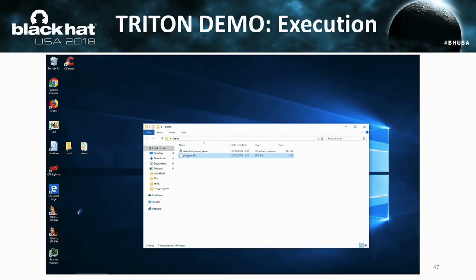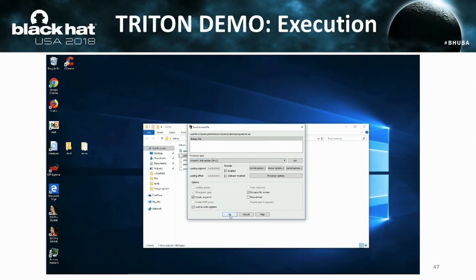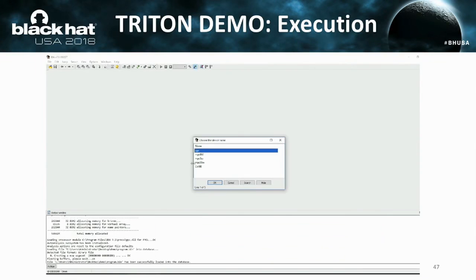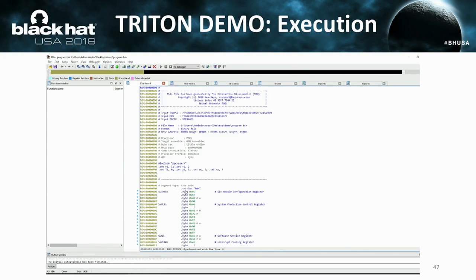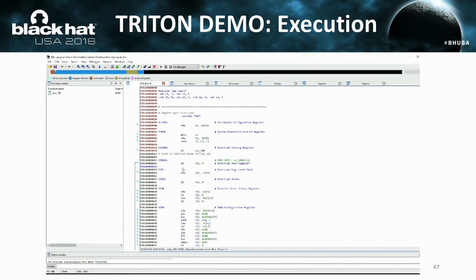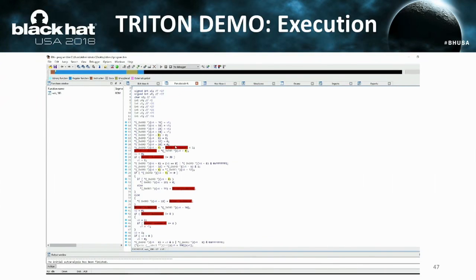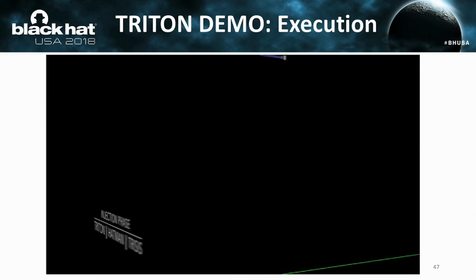Exactly. So now let's start to speak some PowerPC. Okay, so we have the target program. We can dissect it with IDA, and based on all the information that we gained so far from the manuals, etc., we can dissect and analyze the program in, let's say, a friendly way. If you remember, sorry, Eunice, at the beginning we showed how important the manual was to identify the microcontroller. That is the key information, because now we can reverse engineer the software that was uploaded, thanks to specific software, because we know exactly for which microcontroller that program was compiled.